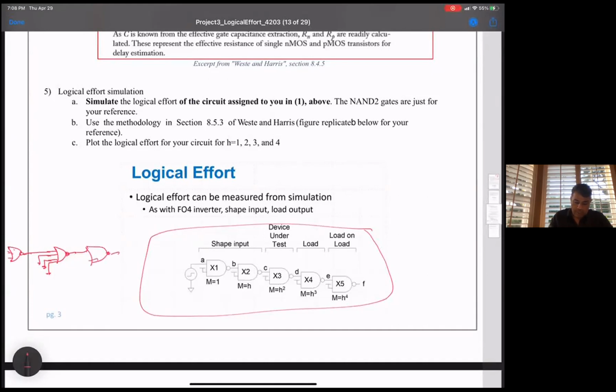Anyway, this point ends up with a really slow rise time and fall time. What people have done in the past where they've gone wrong is they've used a really fast input, in terms of the period of the input, so that the output at some point along the line doesn't make a full transition to VDD.